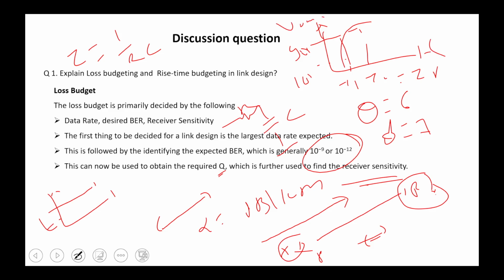It is only a low pass response, because of the bandwidth. I just explained that an RC circuit may be low pass or high pass. We do not consider the filter here, we just consider the circuit with C here and R here. It may be high pass, but we take the capacitance of that circuit and the load resistance of that circuit to calculate the rise time at the receiver side of the signal.